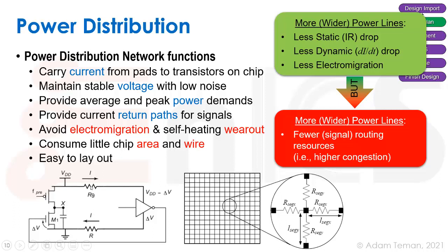But the thing that happens with digital chips at least is every time we have a rising edge of a clock, we start a whole bunch of these toggling operations, which cause a spike in the current drawn out of VDD, or current drawn to ground at one point, and then it settles down.